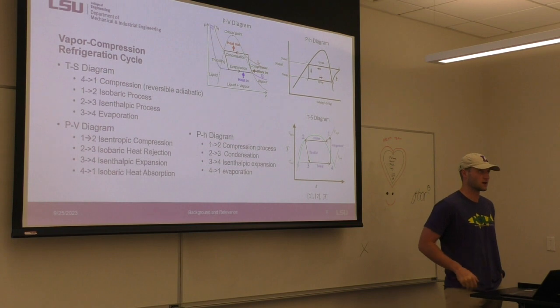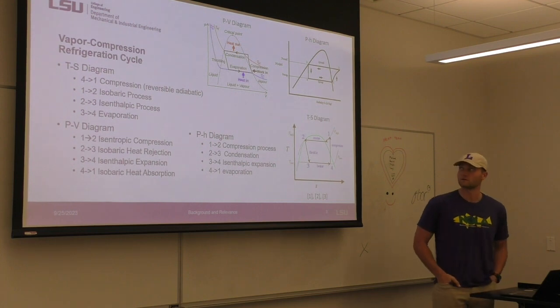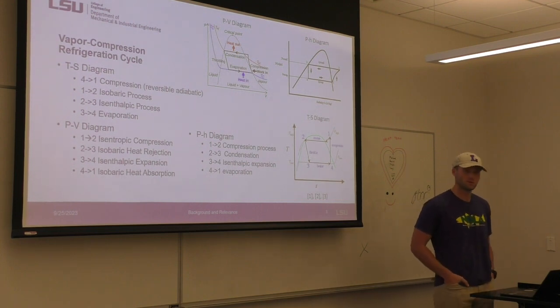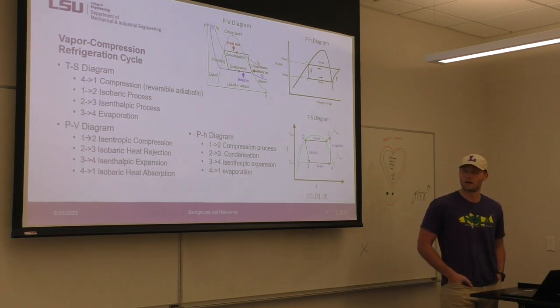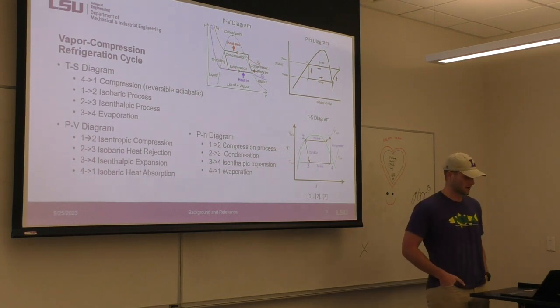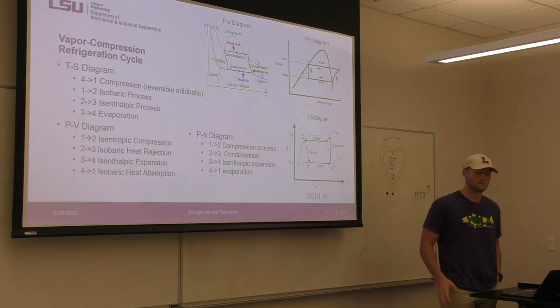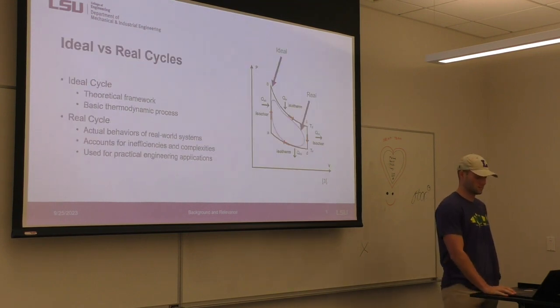And then you get to the condensation phase, where your heat will actually be leaving the system itself, and heading into the throttle phase, which decreases the pressure, once again pushing it into the evaporator again. And that throttling phase is done using the thermostatic expansion valve, which I'll get into how that works in a second. But there are different ways you can show the system.